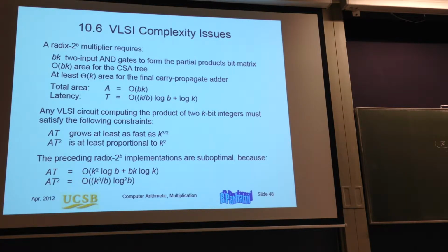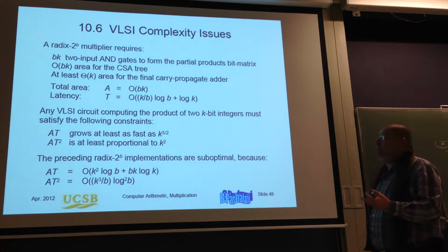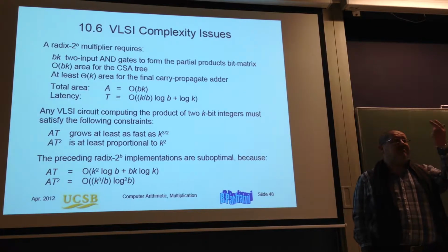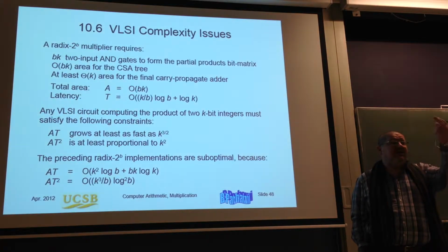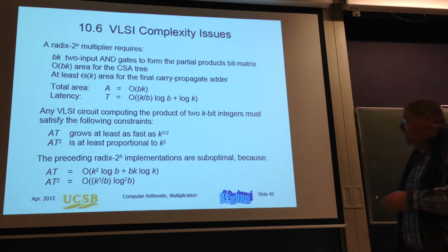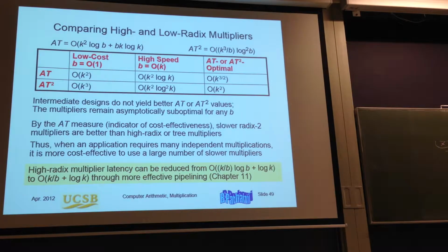Now, if you could generate the partial products with a different technology, and you could represent digits directly in hardware, those would no longer be AND gates, but some other kind of multipliers. But because the easiest solution is to rely on binary representation, you have that number of AND gates, then you have a reduction tree, and then you have the final adder. This is the standard approach for fast multiplication. I won't go into too many details.